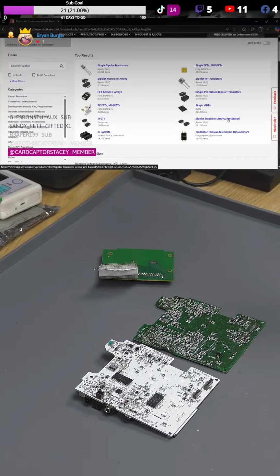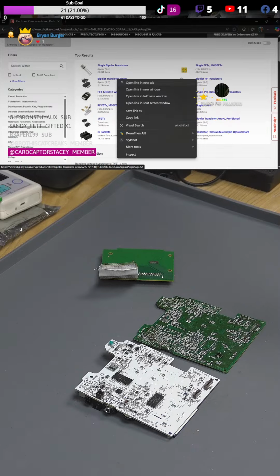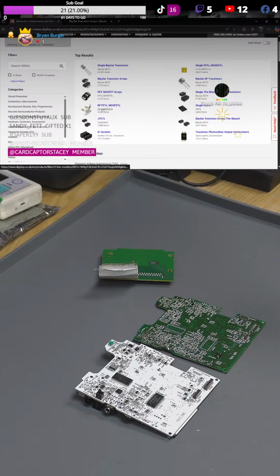It might be that. It won't be single diodes or single transistors because they're 3-pin. We don't care about FET arrays. It's very unlikely. All these are unlikely. JFETs are unlikely. Singles and FETs aren't likely. So the only thing we really have is, it's not going to be a single pre-bias because we've measured 3 diodes. So it has to be at least 2 transistors of some form. So we're down to BJT arrays, which are probably just going to be straight arrays,